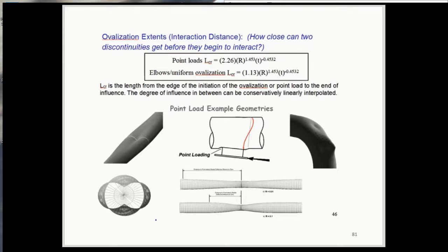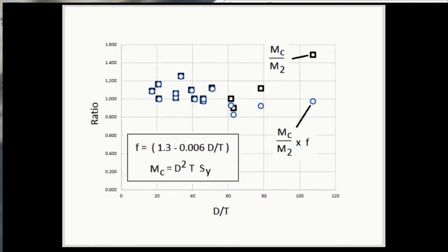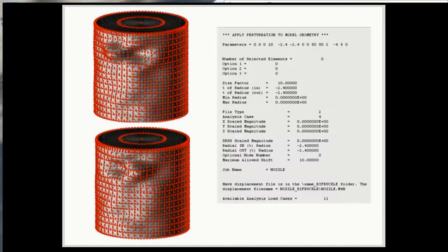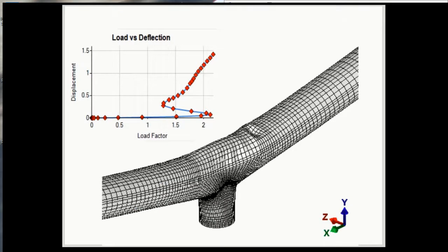Certainly with the buckling behavior of large diameter pipes and vessels, with the code equations that address the behavior of these large diameter pipes. Nozzle Pro includes updates, for example, that simulate fabrication perturbations that can result in minimum buckling loads, buckling and wrinkling of large T's in compressive bending states in D over T ranges less than 100.